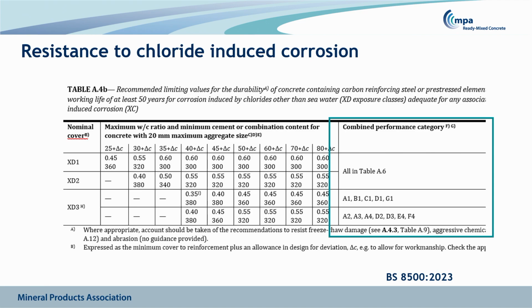Now, the other thing to note in here is that it was decided that strength was no longer required as a limiting value for these. And in fact, it could be problematic, because obviously some of these lower clinker cements may not have particularly good characteristic strength. If you put a limiting value of strength in there, you're precluding their use for no particular reason, when really the performance is being driven mainly by water-cement ratio and maybe partially something to do with the total binder content. But that's been removed.